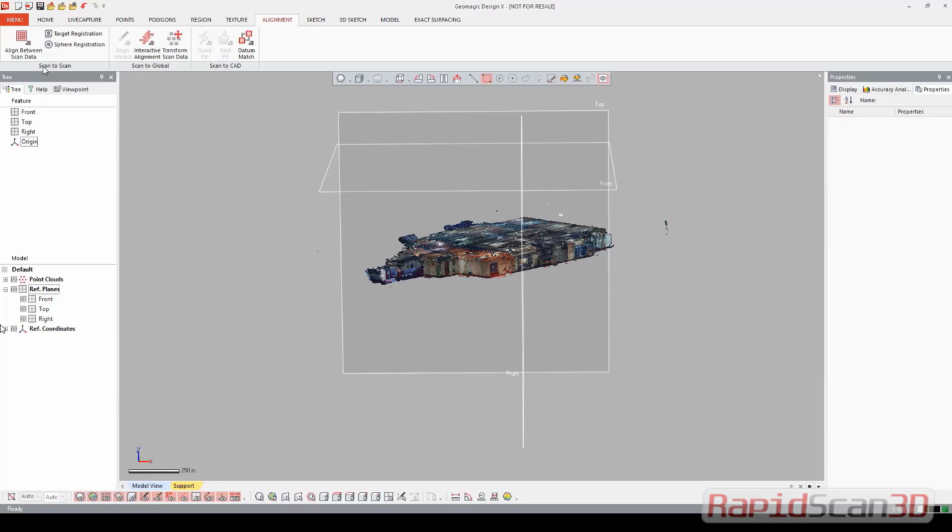The target registration command aligns scan data automatically based on the target information of the scan shots. It checks a specified data folder for scan shots as they are created and imports and aligns data in real time. Scan data can also be aligned to either nominal target points or other scan data that has corresponding target points. In this instance, normal pick point is also fine. But after the scan data has roughly been aligned, then you run the Global and Fine tool, which aligns scans based on geometric feature shapes with the lowest amount of deviation possible in overlapping areas.